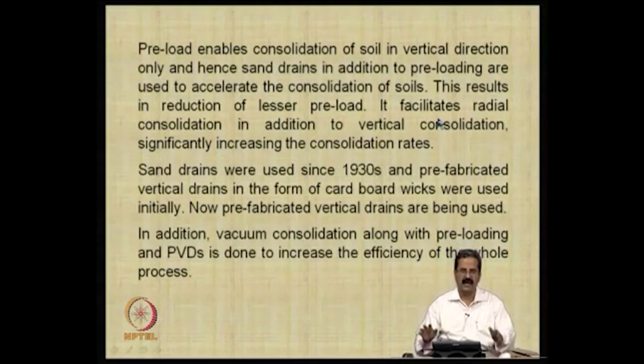As I just mentioned, our objective was to increase the rate of consolidation, and preloading was requiring a very huge amount of preload to be applied. Here we are able to have a good combination and come up with radial consolidation in addition to vertical consolidation, significantly increasing the consolidation rates.